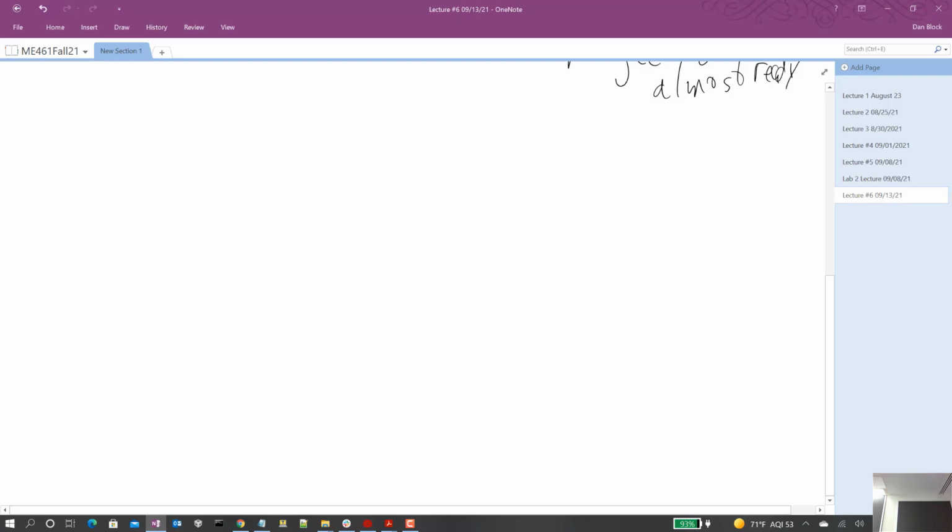And so this, hey, I'm talking to you, sometimes is done with an I/O pin. Exactly the same way you turn on and off an LED. So the same way you set it high to turn on an LED and set it low to turn off an LED, you, in future labs and future work, outside of this class too, you'll be using digital IOs to maybe turn on a chip and say, hey, wake up. I want to talk to you. It's called a chip select. And that's done many times with a standard GPIO.